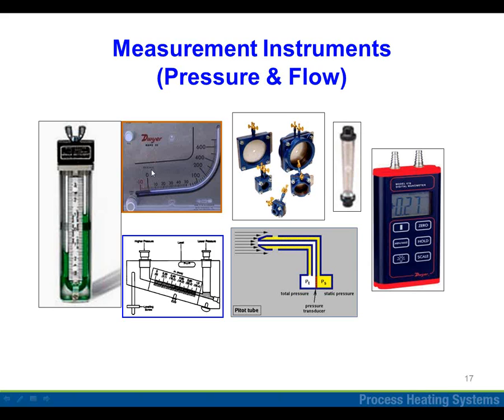If you look at the furnace pressures, they are not going to be in terms of 2 inches water column or 2 psi, but they're going to be in terms of 0.5 inch water column or 0.2 inch water column. And you need these inclined tubes, top and bottom. So either one, there are 2 different types of things. There are digital instruments available, but again, you need to have proper calibration means to do that. And inclined tube manometers are used for low pressures also.